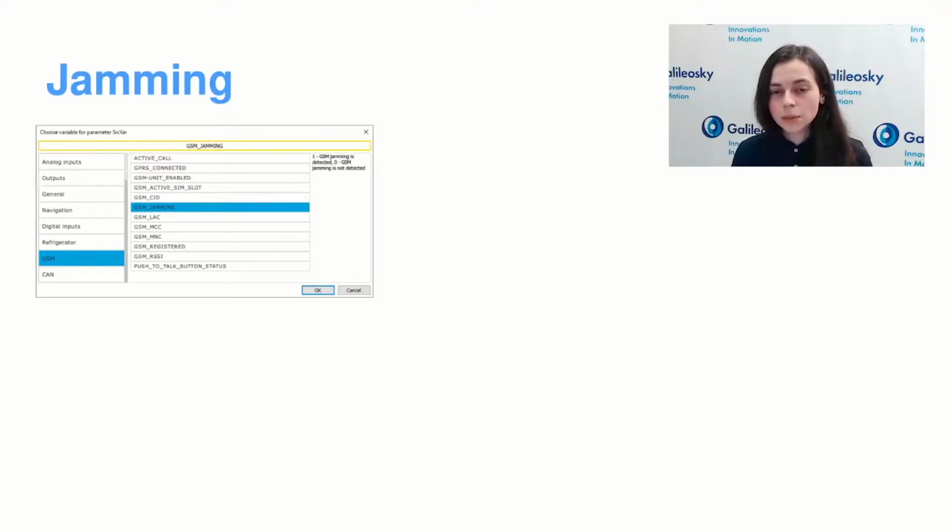And please be very careful using this variable, because they suppose that the device is jammed, so somebody wants to steal it, and in order to switch it off this way, they use some additional equipment, and they block, for example, the engine. Please be very careful, because first of all, people can be killed if you block the engine line, for example using a relay in Easy Logic when the vehicle is moving.